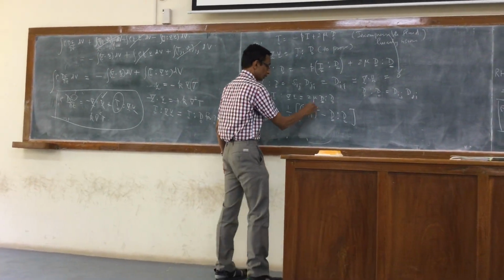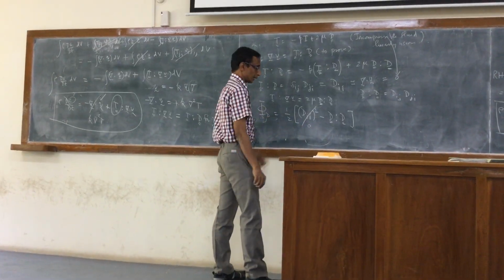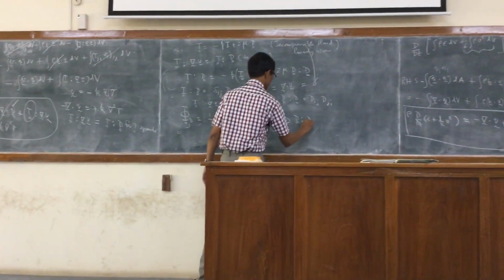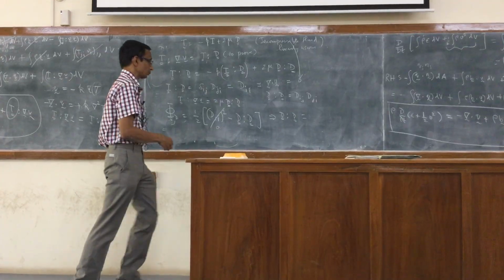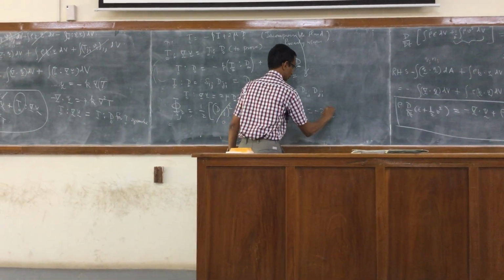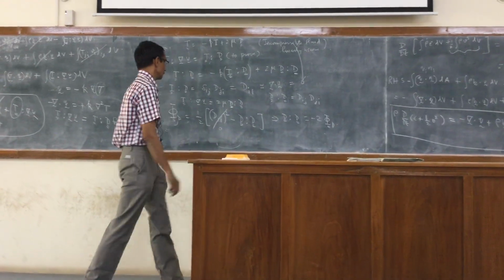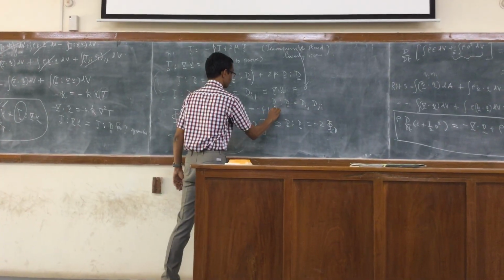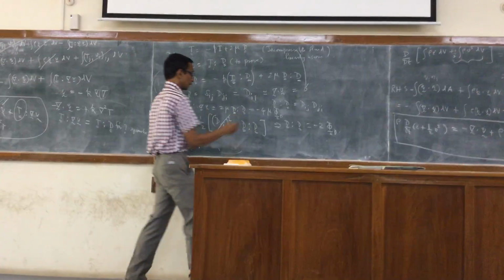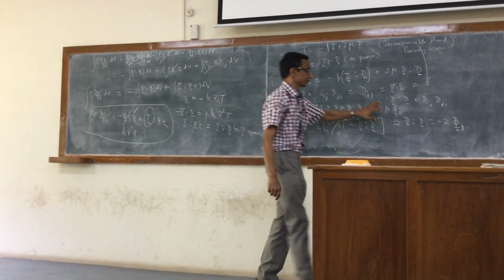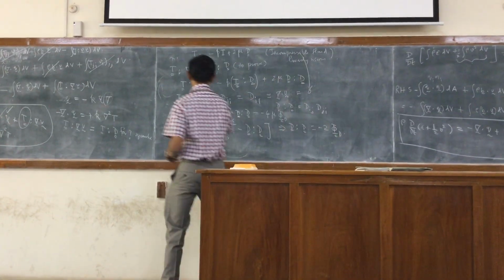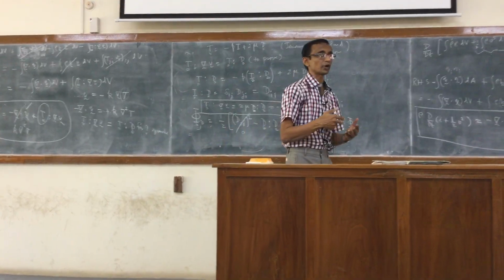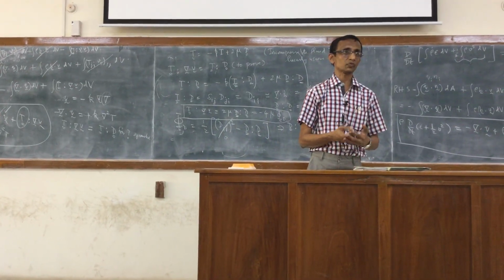So now for an incompressible fluid dii is 0, which would mean that D double dotted with itself is actually given by minus 2 times the second invariant of D. So sometimes it's also written as minus 4 times the dynamic viscosity times the second invariant of D. So this sort of completes the evaluation of the viscous dissipation term for an incompressible linearly viscous fluid.